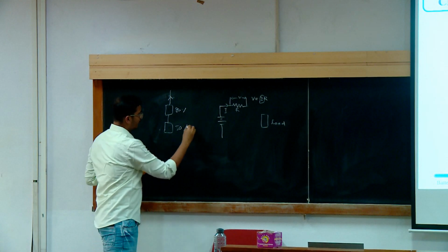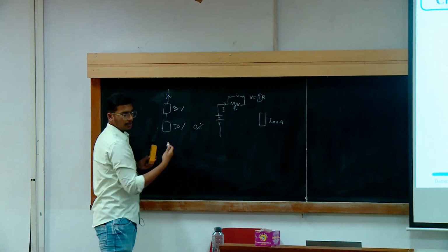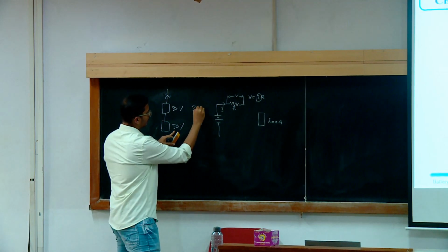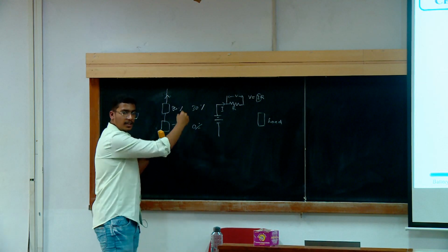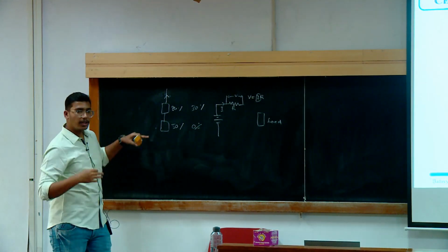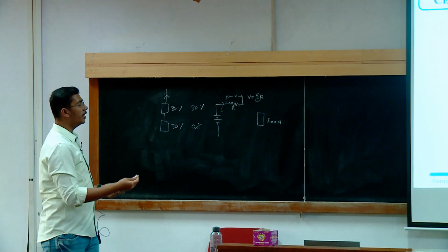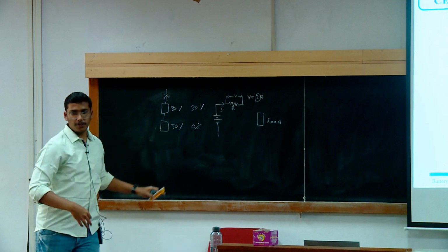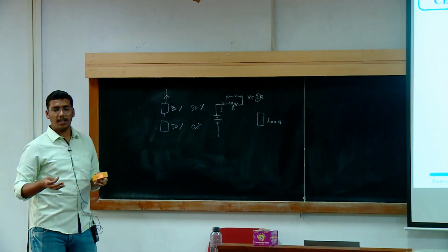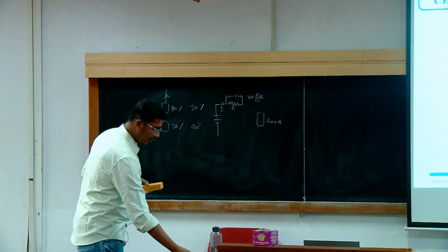When one comes near 0, we should not go to 0, but the other will only be at 30%. It has some capacity still left, and this one has reached its end point. Then the cell with capacity left will say, I am fine, you can still keep on discharging. That will lead to deeper discharge of the other cell, which can eventually damage it. If any of the cells in a string gets damaged, the whole battery pack fails. That's why cell balancing is essential.